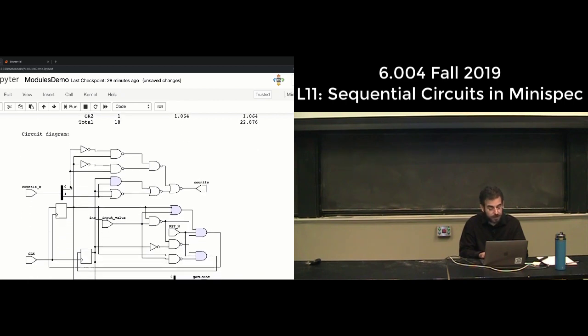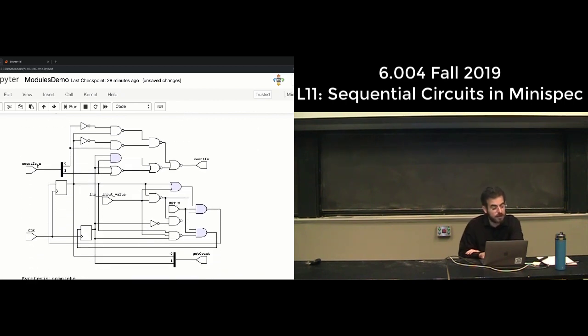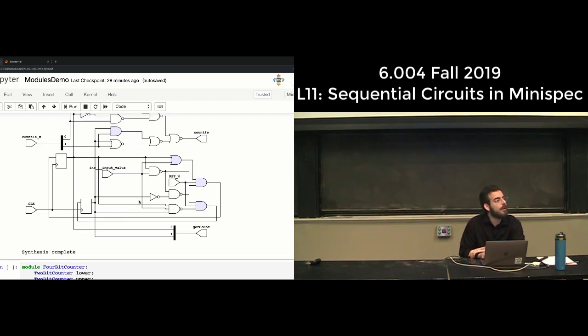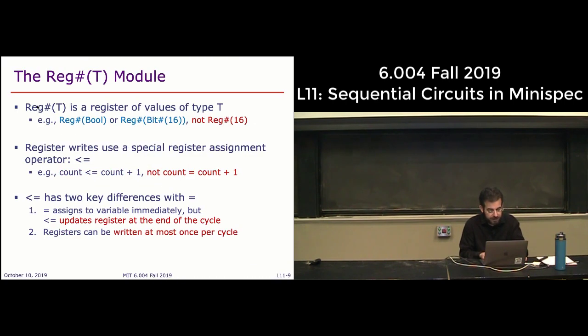The way this shows up in the circuit is you see that there is this new input, count is x. There's a bunch of logic that will take the current state and the argument, and then give you the output count is. And then, of course, we have the previous circuit, exactly the same as before, with get count, clock, inc, and so on. Okay, any questions? So you can see that this is a fairly straightforward way of specifying what a sequential circuit does.